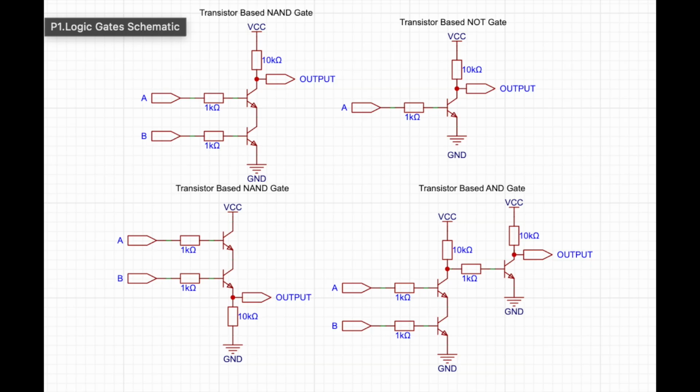The original AND gate design works by putting the output on the other side of the two input transistors, meaning that current should only flow when both A and B are high. However, because of transistor leakage from the base pin to the emitter, if only B was high, there would still be some voltage flowing out the output, giving us a high when there shouldn't be one.